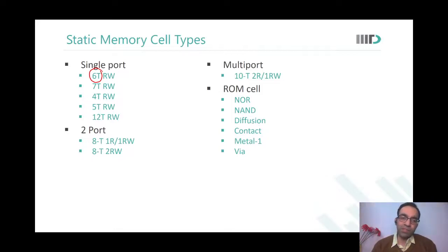It depends on what are the specifications. If the 4T cell is designed such that it has a huge current and the 6T cell is designed such that it is a high density cell, the 6T cell could be smaller than the 4T cell. We just talked about it in the last slide, right? Depending on the optimization, a 6T cell could be denser than a 4T cell or a 5T cell. Also the layout, physically how I am placing those 4 transistors, what are those 4 transistors? Are they all PMOSes? Are they all NMOSes? Are they PMOSes and NMOSes? That could also change the kind of area we are talking about.